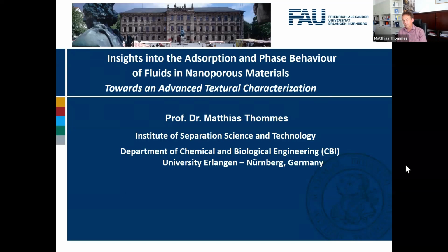In order to do an advanced characterization of nanoporous materials, it has been shown over the last 2 or 3 decades that a fundamental understanding of adsorption behavior and how the effect of confinement changes the phase behavior of fluids in pores can be a tool essentially to do an advanced texture characterization.